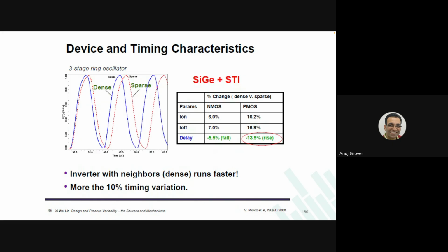Metal 2 may be made thicker or thinner, and metal 3 could be on the other side of the acceptable specification criteria. And the resistances of the two lines could be very, very different. So whichever signals you want to match, they should be drawn in the same metal.